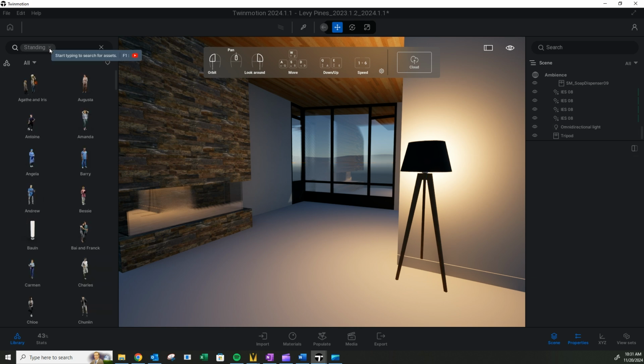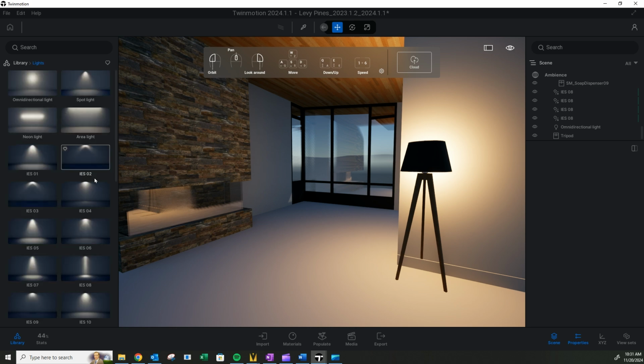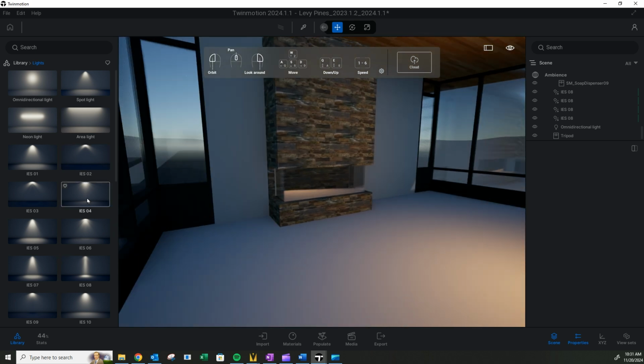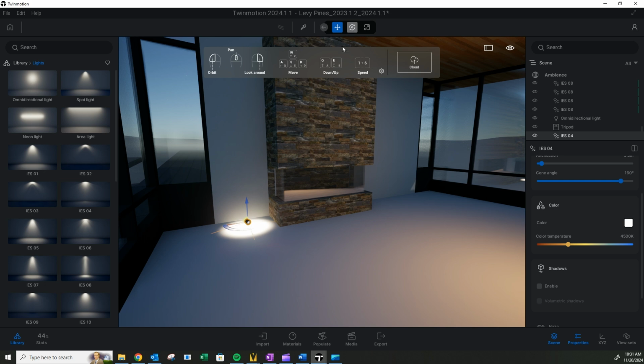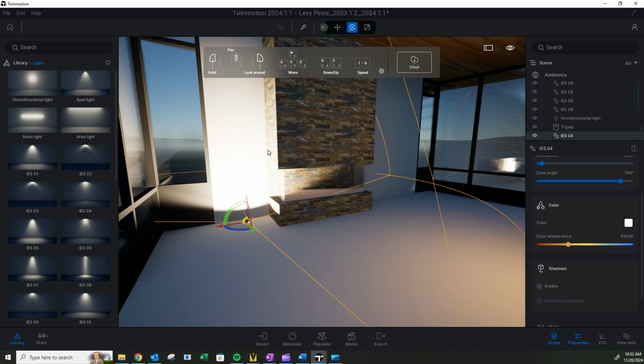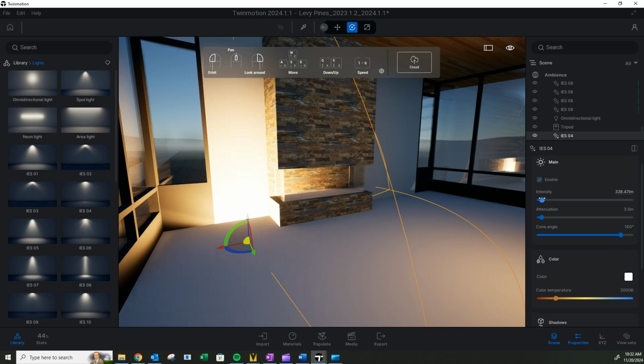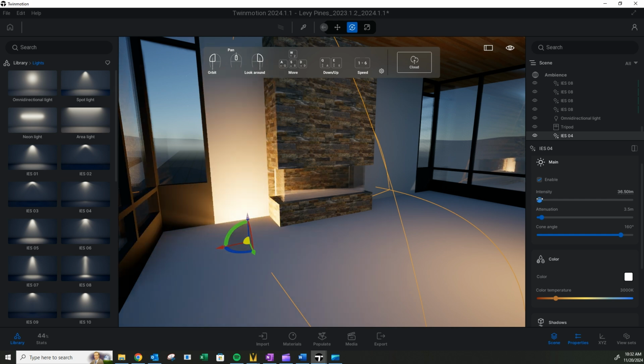The other thing is, in your downlights, even if you're doing an uplight, you can pick out fixtures that have IES files on them. Quality fixtures will have IES files where they study the IES, and also can have certain kinds of optics that reduce glare, so that the light source itself might be tucked back into the fixture, or maybe it has a honeycomb type louver. That way it's not quite so harsh.